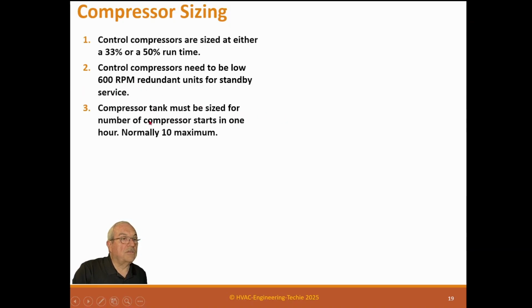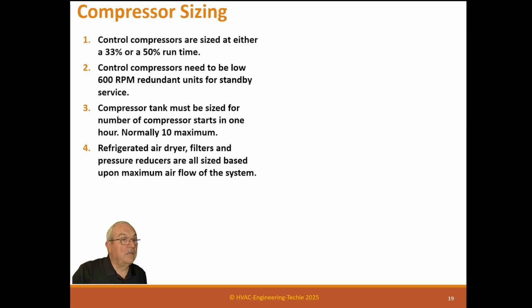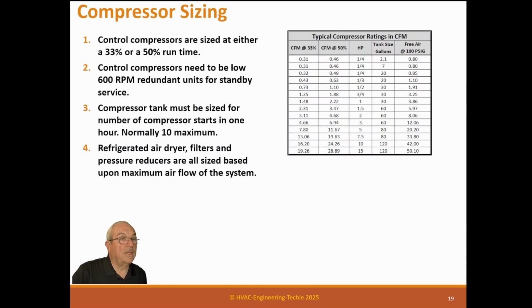For standby service, compressor tank must be sized for the number of compressor starts in 1 hour, normally a maximum of 10 starts an hour. Refrigerator, air dryer, and filters, pressure reducers are all sized based upon maximum airflow of the system. And this is the typical compressor ratings of CFM.